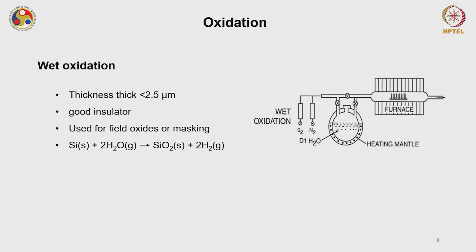For a little thicker oxide you mostly use wet oxidation. Wherever you need a much thicker oxide, you should choose wet oxidation. Although the quality of oxide grown by dry oxidation is pretty good compared to wet oxidized wafers, it requires a lot of effort to grow thick oxides using dry oxidation, so we should always avoid dry oxidation for thicker oxides.